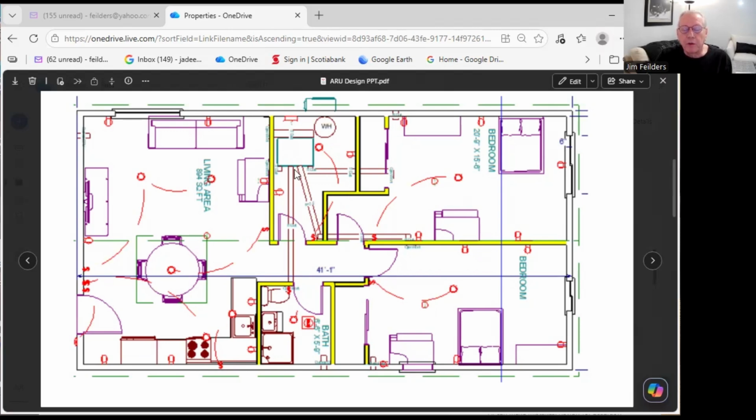And then for heating and cooling, there will be a ceiling hung concealed unit heat pump. The outdoor unit is on the outside back wall, and inside is the unit. It takes return air from the open living area into the back of this unit. And then there's ducting to 4 areas.